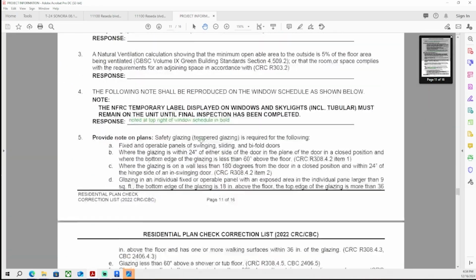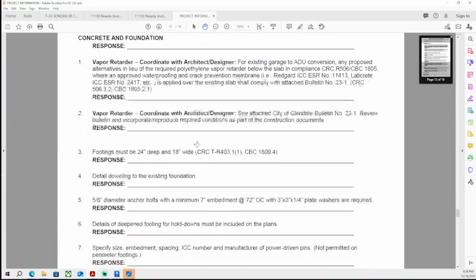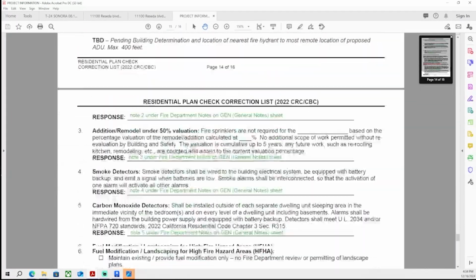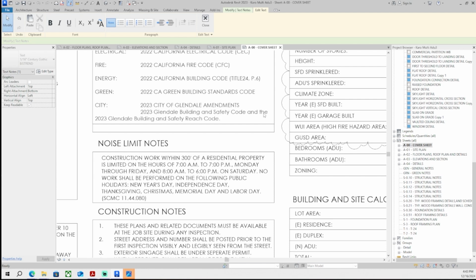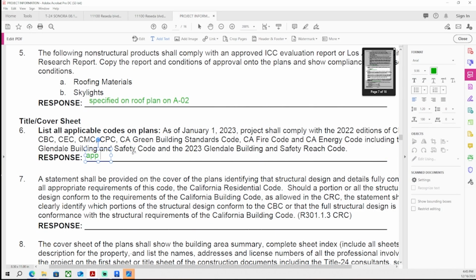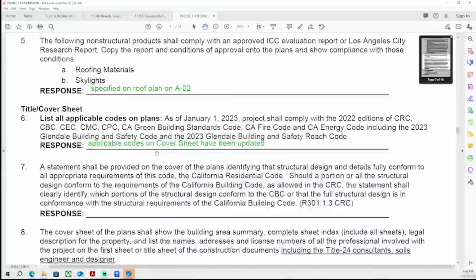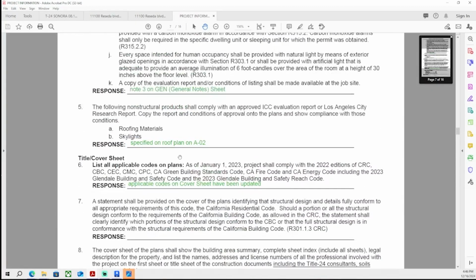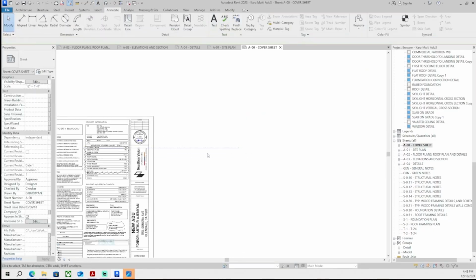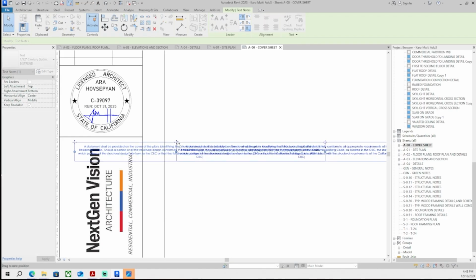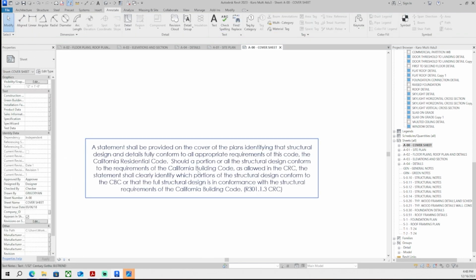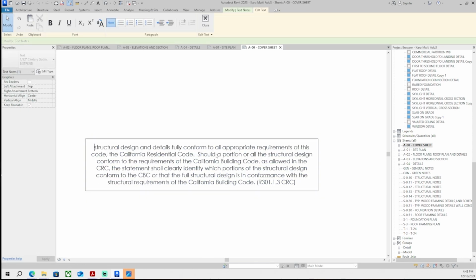The CRRC is the Cool Roof Rating Council. So it shows you that this roof has been rated and it's not going to have a lot of heat transferred from the exterior to the interior. And the SRI is the Solar Reflectance Index. It's the indicator of the ability of the roof surface to return solar energy to the atmosphere.